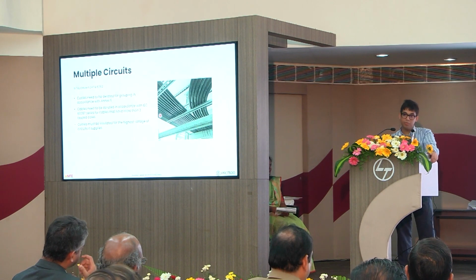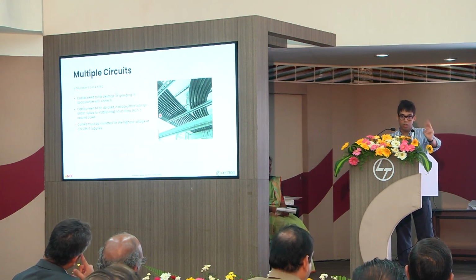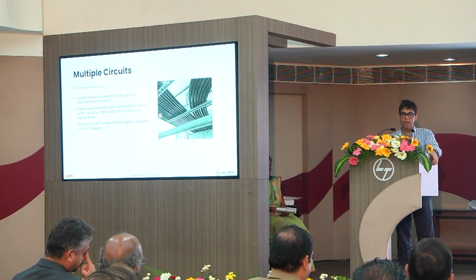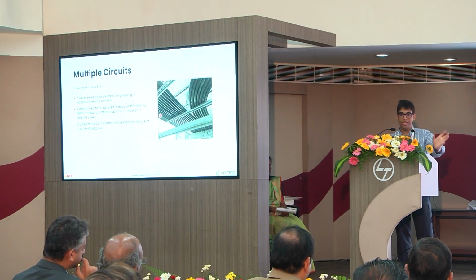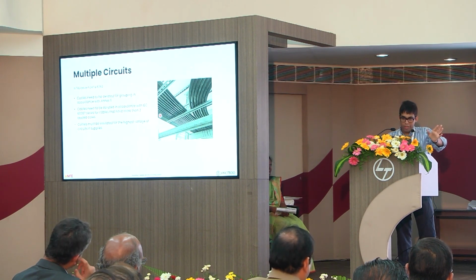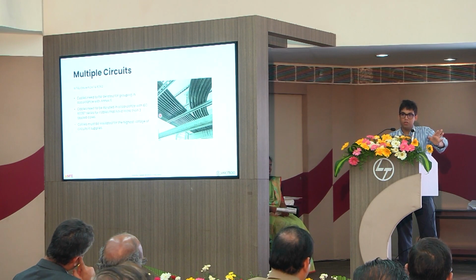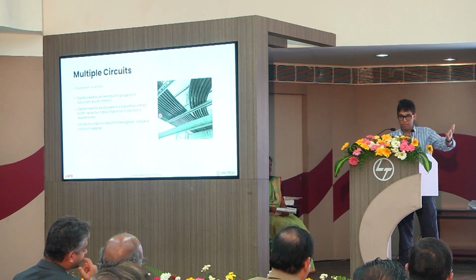Additionally, if a cable has more than 3 loaded cores, so again, when it comes to harmonics, there was a gentleman on the NFE group who was saying that let us use a 5-core cable and let's have 2 neutral conductors. Not a very conventional idea, but I'm not saying that it is wrong. Maybe from other points of view, it is not a very good idea, it is probably even non-compliant.